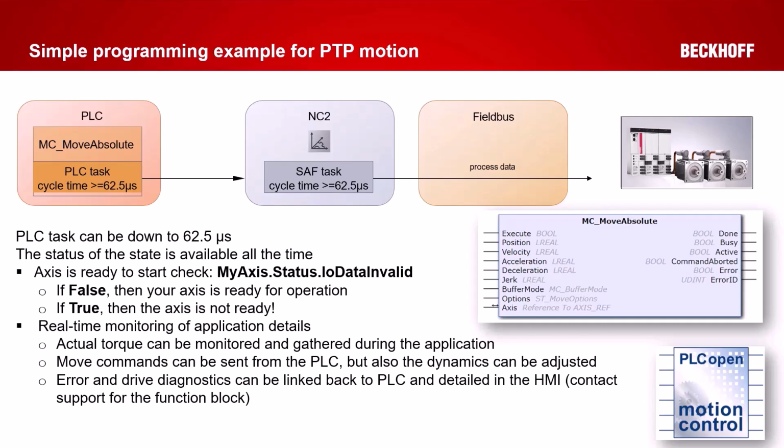You can read the torque, you can put that back into your application. You can issue move commands in which you can specify the dynamics and really make it blend well in your application. And you can read the error and the drive diagnostics in real time. You can put that into the HMI, put suggestions on what is causing the error. And we offer a full supported function block for all of our axes that is available. Just contact us.